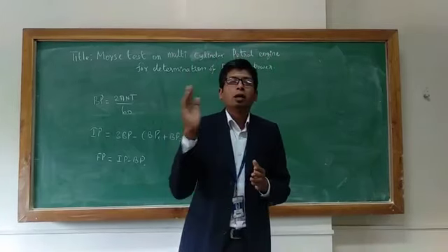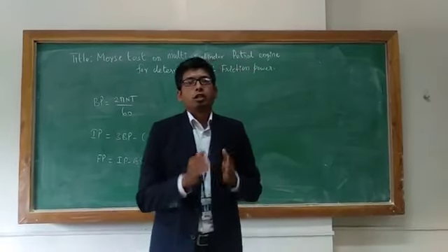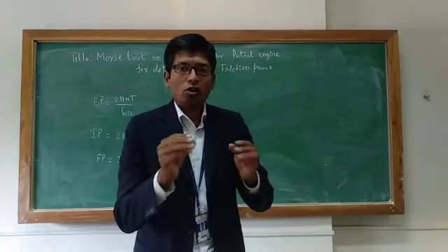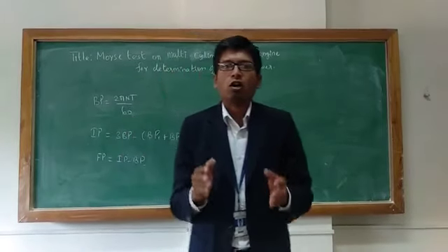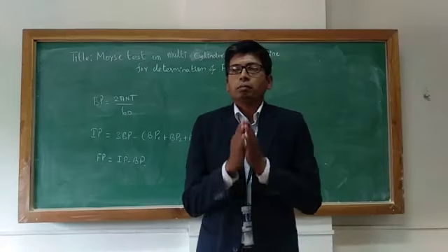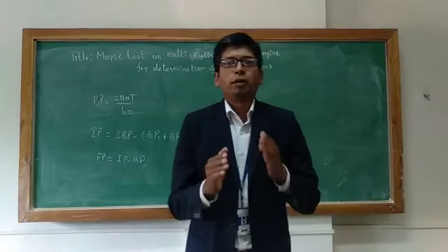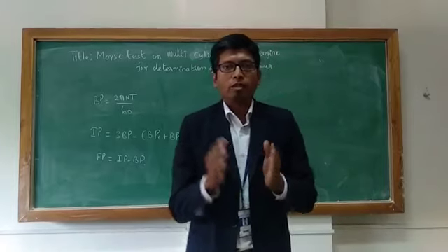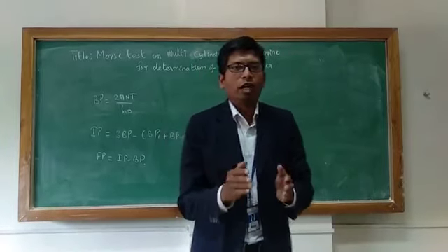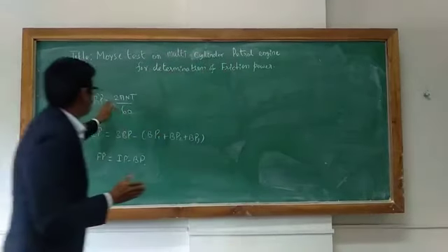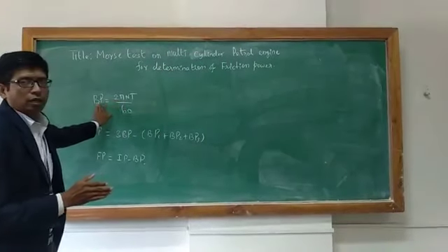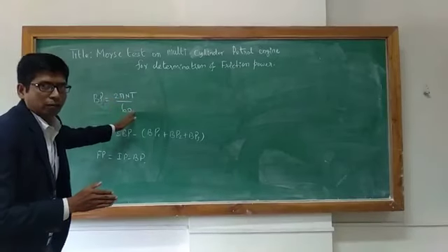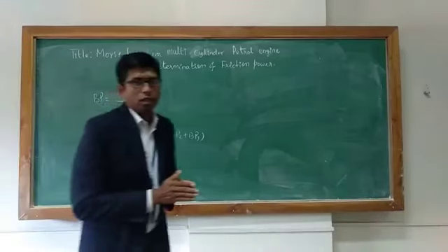Now, we are having the petrol engine. In the petrol engine, we first run all the cylinders at a particular speed and keep the speed constant. Now, we measure the load, that is, the torque. With the help of the torque, we get the brake power, that is 2 pi MT upon 60, when all cylinders are working.